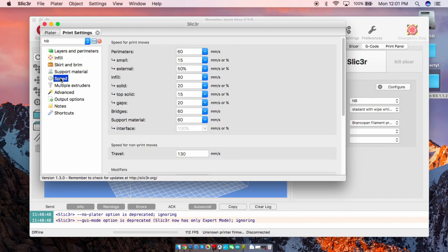And then we have the speed tab. The speed tab determines how fast your print head can move during different types of operations while drawing your part on the print bed. These are my standard print speeds that I use for all of these operations, and I'm going to use these across all of the different profiles that we make today. These are really calibrated towards my printers. Works pretty good on the Ender 3. You may or may not tweak these.